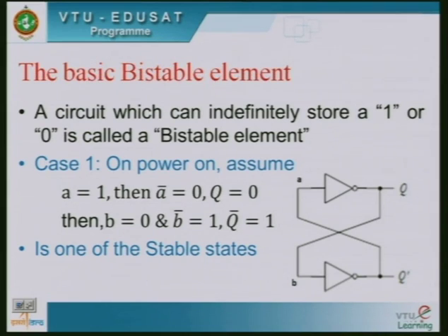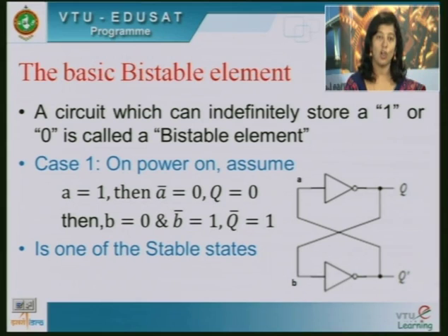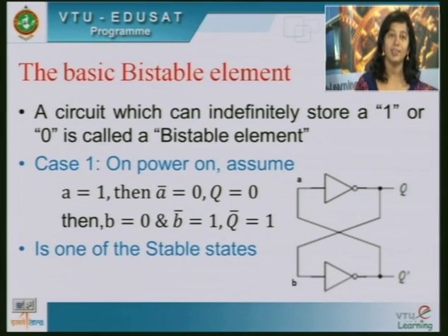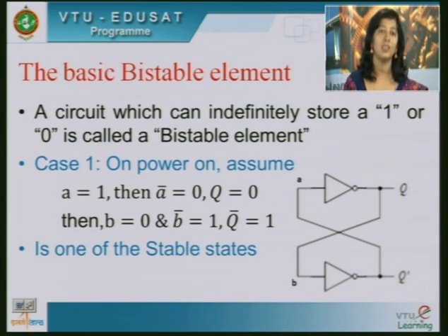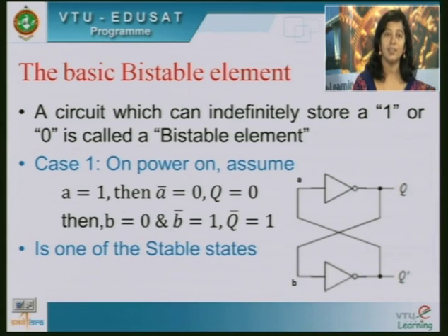Next, let us see how to build a latch or a flip-flop. The basic element needed to design a latch or a flip-flop is called a bistable multivibrator or a bistable element. As the name indicates, a bistable is one which has two stable states. One is the high state, the other is the 0 state. So, a bistable circuit always has both stable states.